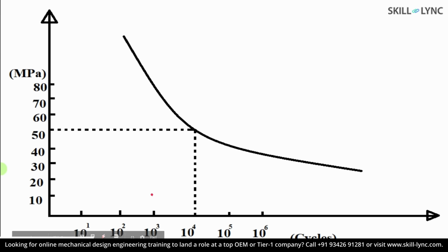Here, let's say I have a material and I want to check the maximum stress that it can take after 100 cycles. So I just extend this point here, and note the corresponding value for the maximum stress that can be allowed. Before you proceed with the fatigue analysis, you need to perform a static analysis on the part so that you understand the type of stress that is developed in your part to predict its fatigue life.